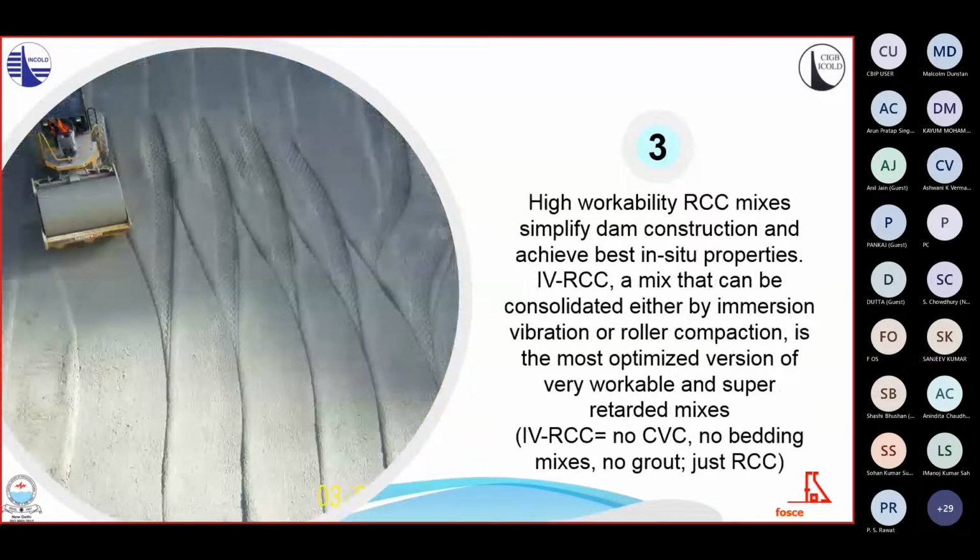And number 3, high workability RCC mixes simplify dam construction and achieve best in situ properties. Immersion vibrated RCC, a mix that can be consolidated either by immersion vibration or roller compaction, is the most optimized version of very workable and super retarded mixes. IVRCC means no CVC, no bedding mixes, no grout, just RCC placed in the dam.